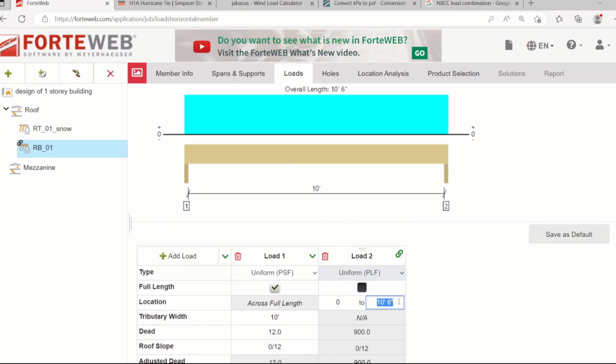Say you decide the truss is only up to 8 foot of your beam, then you can update it here like that. But since this is full span, we will input 10 foot 6 in there.